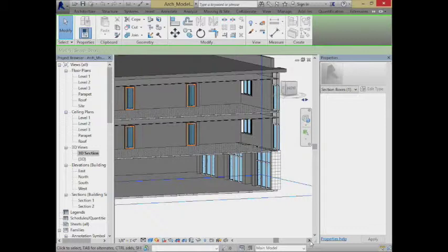So, for example, we often try to run the ducts under the structure. Or if the structure has open webs, we can run the ducts through the structure, okay, we can run it through here. But they tend to exist as a whole layer to themselves, and they tend to go second just because they're pretty impactful in deciding the ultimate order of things. Now, of the plumbing systems, let's talk about them next. I'll give you that one. It's definitely plumbing, number 3, so it tends to go third.